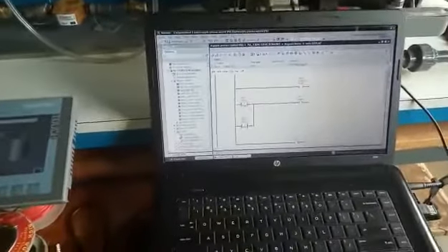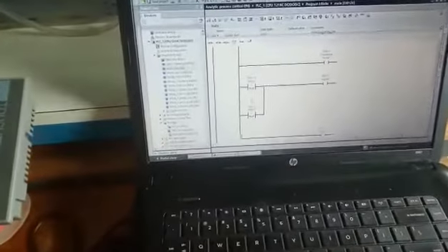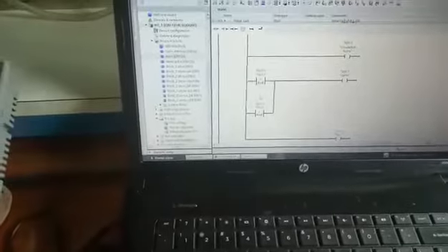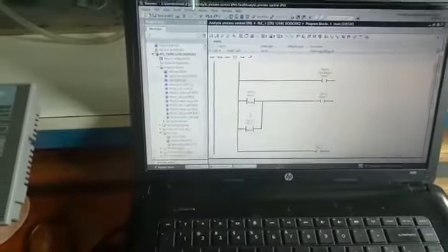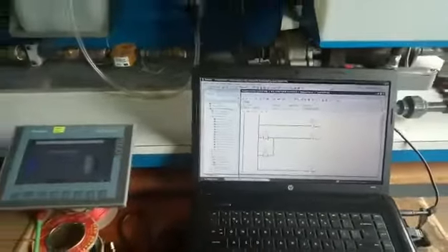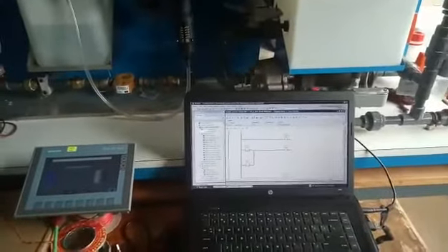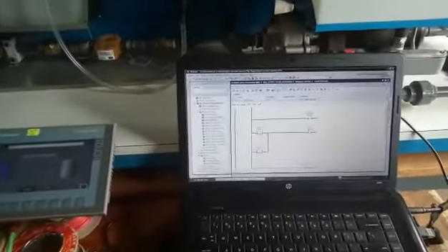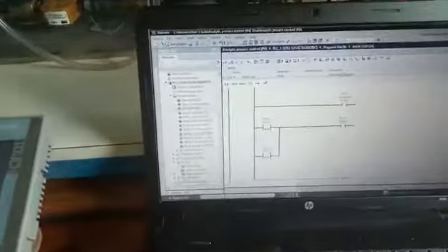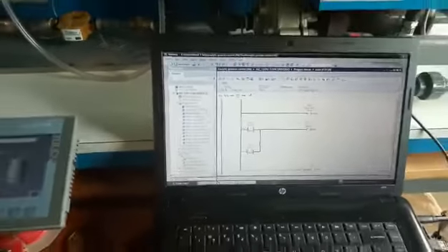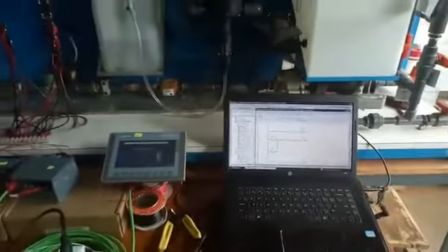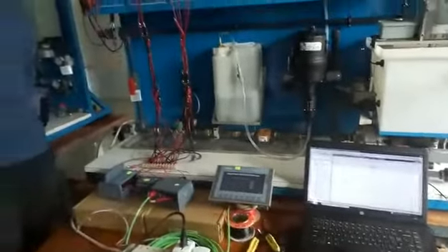For the alarm, we have set some conditions here: the alarm will turn on only when the pH is less than 2.0 and greater than 12. The tag 1 here is used basically to incorporate another program for the PLC, basically for controlling the metering pump. And that's it. I want to introduce my colleague here, Isaiah Nasima, to take us through the connections.